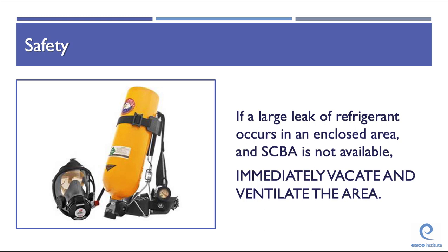In the event of a large release of refrigerant in a confined area, a self-contained breathing apparatus is required. If a large leak of refrigerant occurs in an enclosed area and a self-contained breathing apparatus is not available, immediately vacate and ventilate the area. In large quantities, all refrigerants can cause suffocation because they displace oxygen. Inhaling refrigerant vapors or mist can cause heart irregularities, unconsciousness, and oxygen deprivation, leading to death. You can drown in refrigerant because you will not be able to breathe.